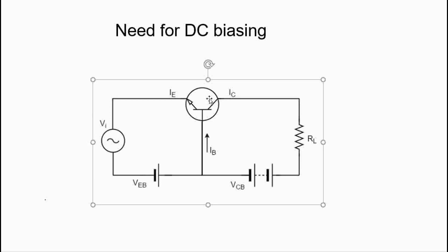Now moving on to the second point. The BJT should be in the active region to be operated as an amplifier. So appropriate DC voltages and currents are given to the BJT by external sources, so that the BJT operates in the active region, and the AC signals to be amplified are superimposed. Then this problem can be avoided.